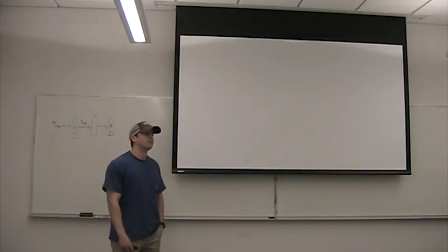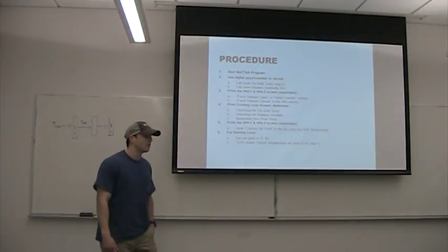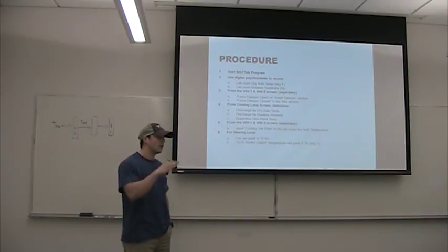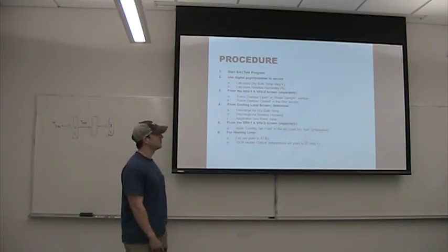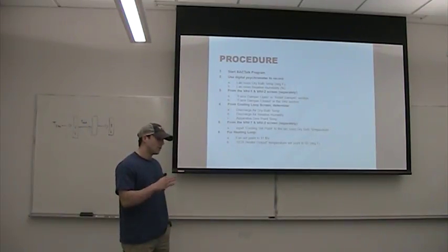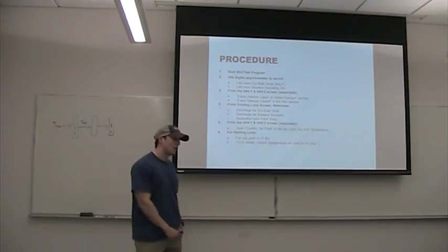Any questions? So what is controlling the opening and closing of the VAV box? It's like a mechanical damper, so it'd be like a valve. It'll open and close. Why will it open and close? To control the volume of air that flows in there.